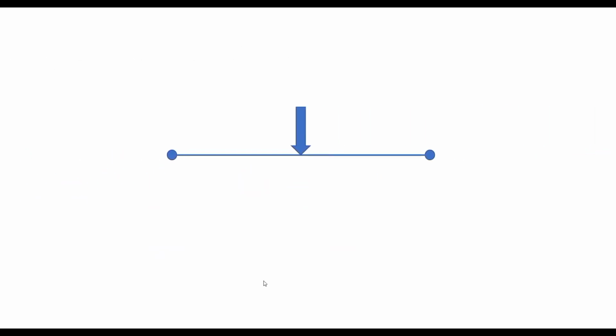look at an alternative solution of stabilizing this beam. In addition to restraining one of the nodes to move in the vertical direction, we also prevent the rotation of the same node, instead of restraining the other available node vertically. So in this case, we have applied both types of reactions on the same node. The other node has been left free to move about.